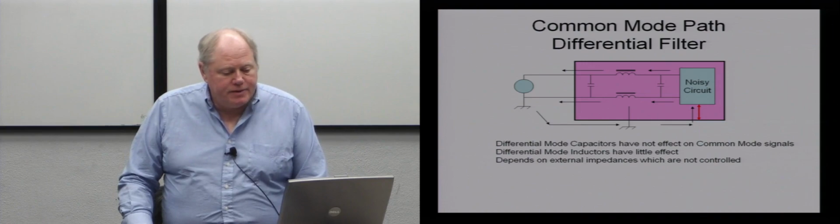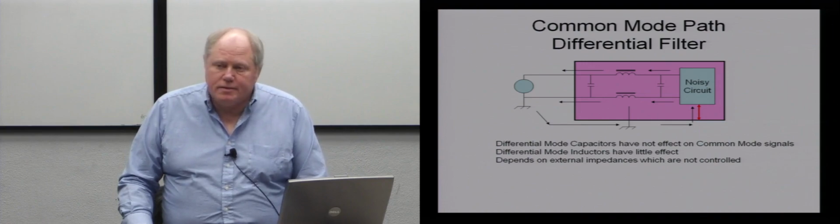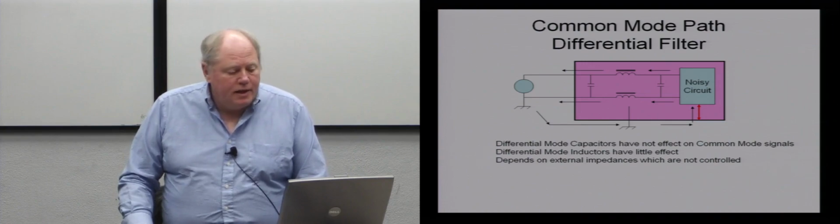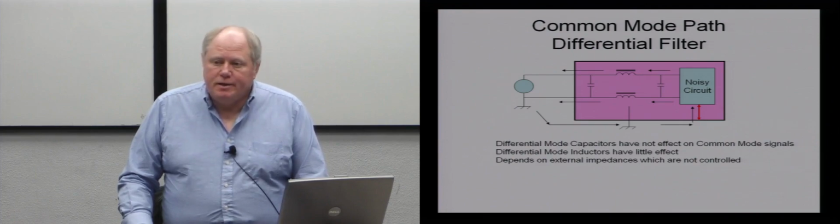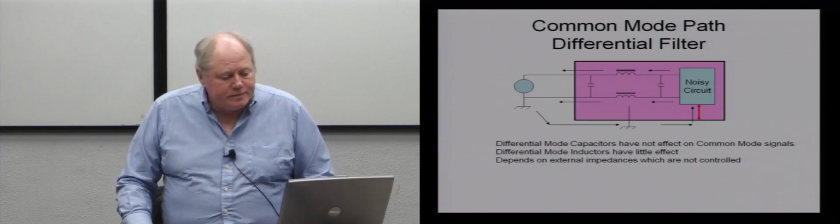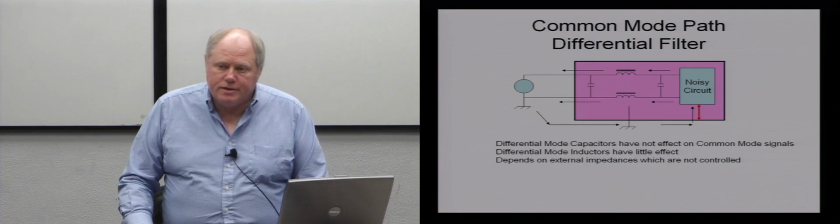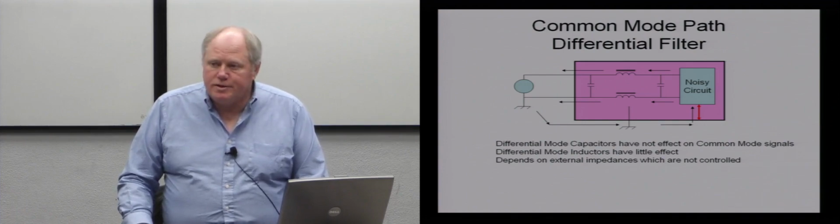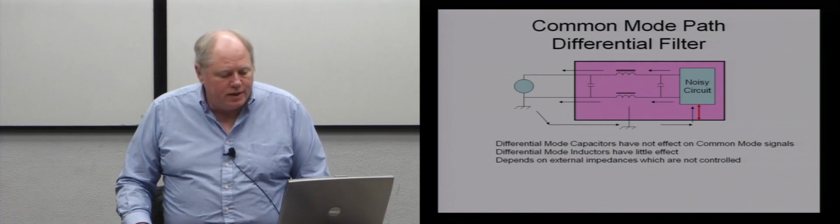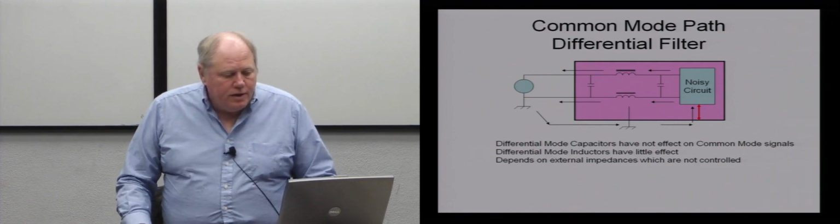But at high frequencies, if you're talking about a signal up at 5 megahertz or something, that wire going down to that panel might as well not be there. It's going to look like a big inductor. So that's going to let this voltage show up at the input of your device, go through that LISN, go through those little capacitors, and show up as a dB microvolt reading that you're going to get.